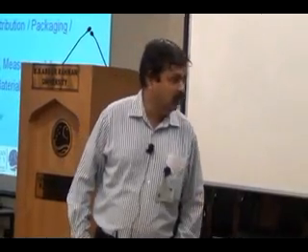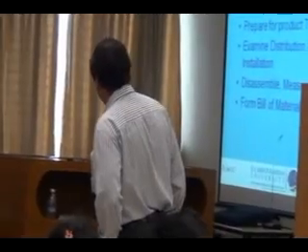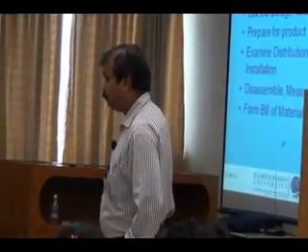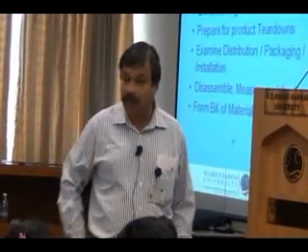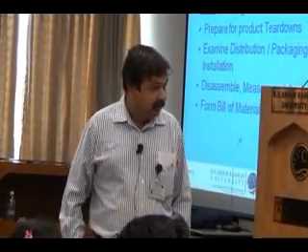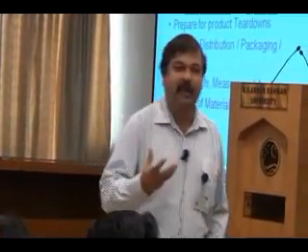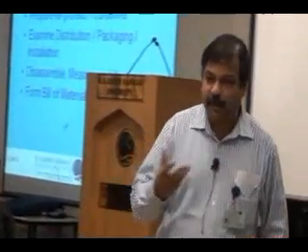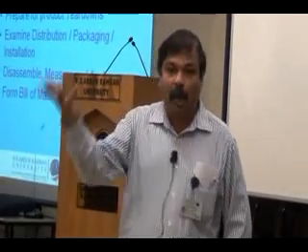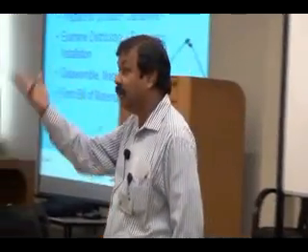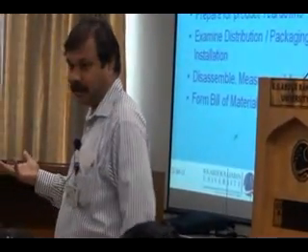Then you have to dismantle, measure and analyze. You have to dismantle, measure whatever you are interested in, and then you have to analyze it. Then you have to form one of the final outcomes of a dissection process. There can be different outcomes. A complete drawing itself can be the outcome. A complete design itself can be the outcome of a teardown process if reverse engineering is the objective.